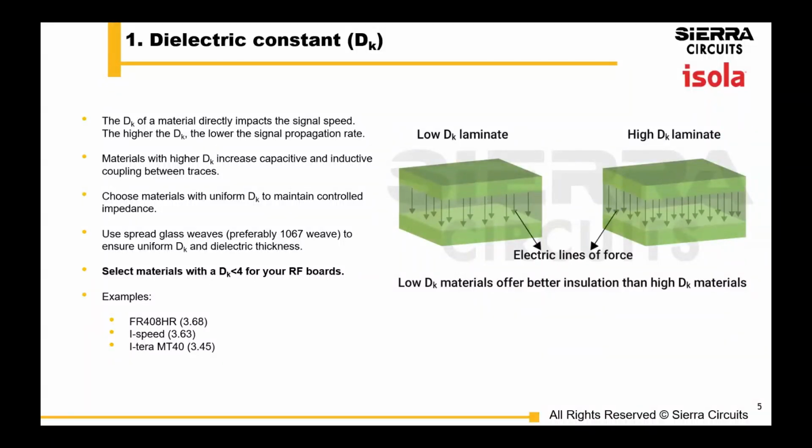The better materials you choose, the less issues you're going to have if you have a high-end requirement, so that's really important. Tilting your board is a solution, but no fabricator likes that solution. Instead, pick better materials with better weave. That's our recommendation.